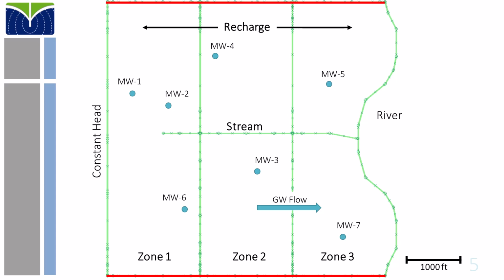You know from geology or soil type reports that there are 3 hydraulic conductivity zones in the watershed, and there is a central stream flowing from the west to the river on the east, and the stream has 3 segments, and there is recharge over the watershed. So those are the parameters you want PEST to estimate for your model: hydraulic conductivity for zones 1, 2, and 3, stream bed conductance for segments 1, 2, and 3, and aquifer recharge.